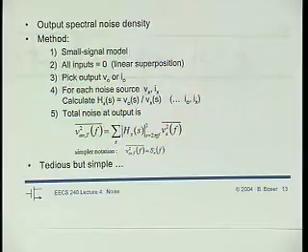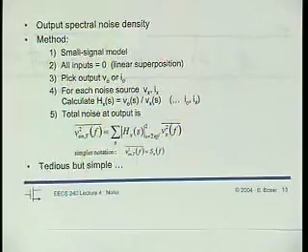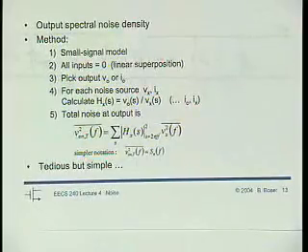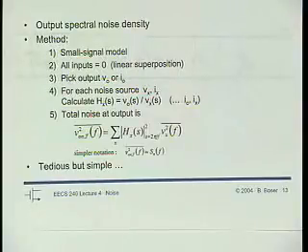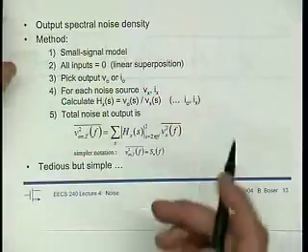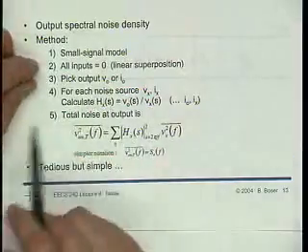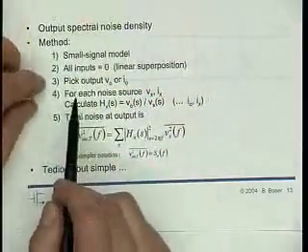And because we are performing our noise analysis on the small signal circuit, everything's linear, and so linear superposition applies. So if we want to later figure out what is actually the output of our circuit with a real input also applied, well, we just add the two contributions together, right? So when we do noise analysis, we set all inputs to 0.